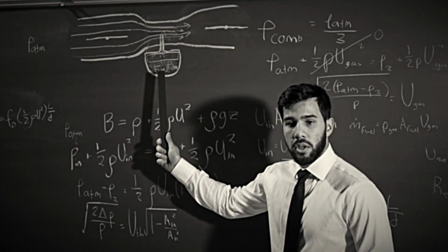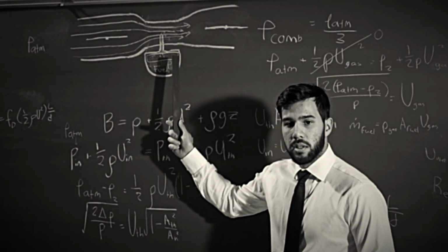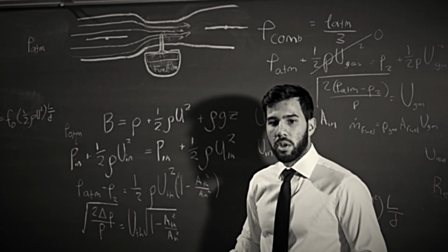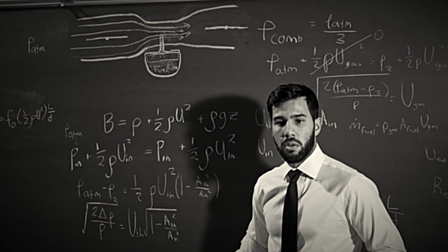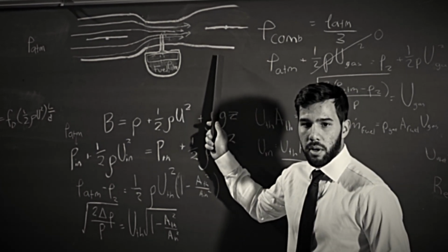This diagram shows an axial cross-section of the carburetor. The airflow channel across this device is the venturi. A choke valve at the opening of this channel controls the inlet flow, followed by a converging region that concentrates air into the throat. A throttle valve behind the throat controls the outlet flow.